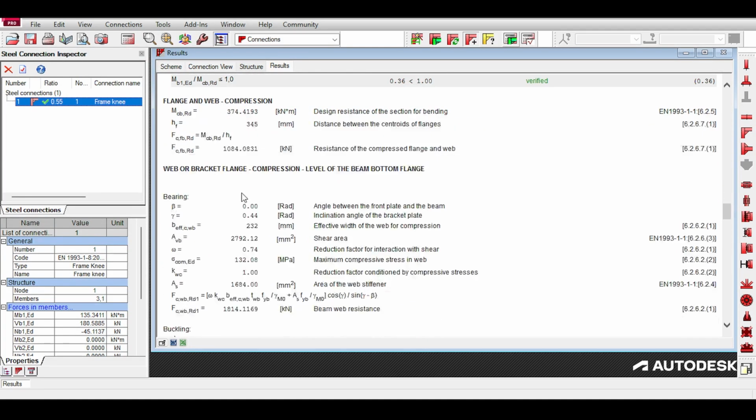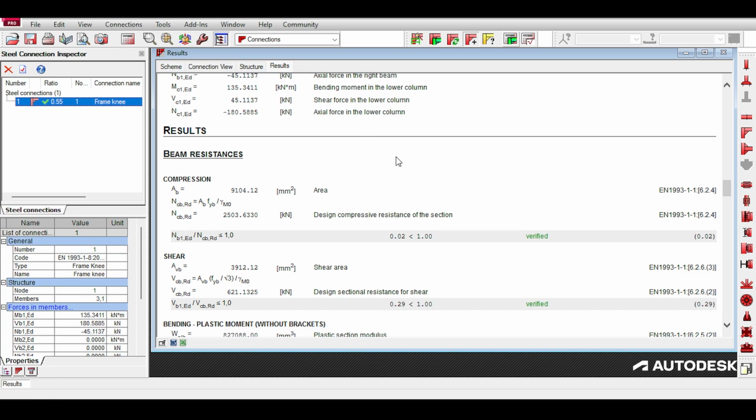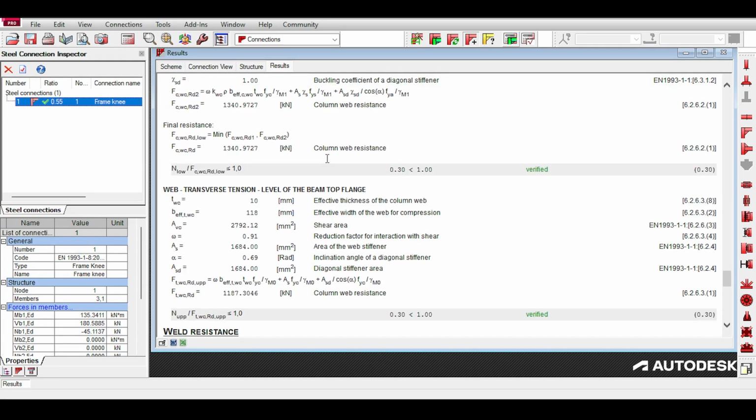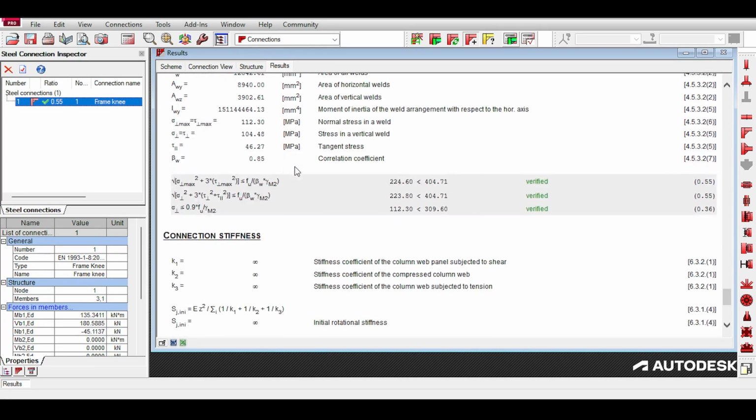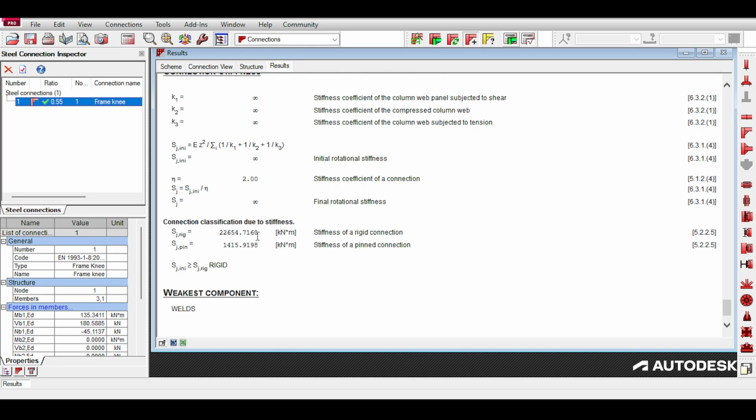Okay, it's doing the welded here. I did a welded connection. Let's see. But I should check that out in the result. Can I see the welds here somewhere? So. Weld. Yeah, okay. Yeah, it does the welding. Okay, fine. And it checks everything. Oh, look. SJ initial. Oh, wow. This is cool for the semi-rigid thing. Of course, here it checks if the SJ initial, which calculates from here, it's infinity.